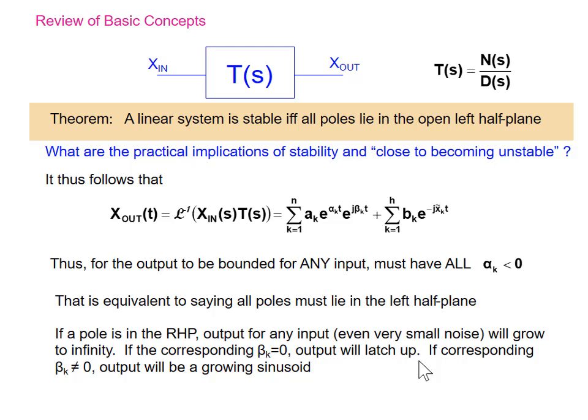I'm not prepared to, well, I can tell you what goes on. If you look at linear models of an amplifier, latch-up's not an issue. If you have an amplifier, they design it so the feedback poles are well positioned in the left half plane for the appropriate value of beta. But you have a nonlinear system.